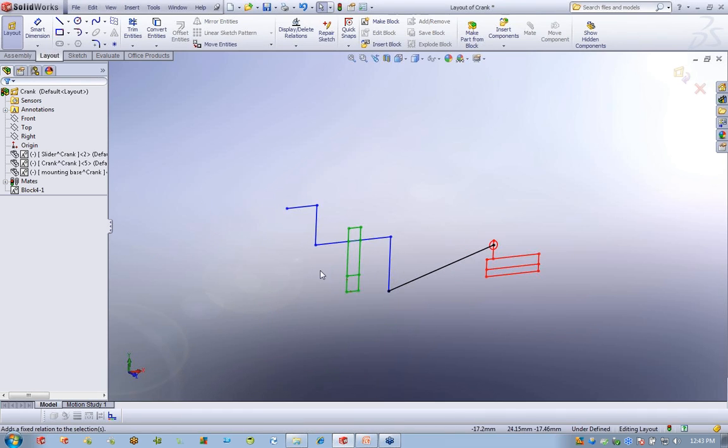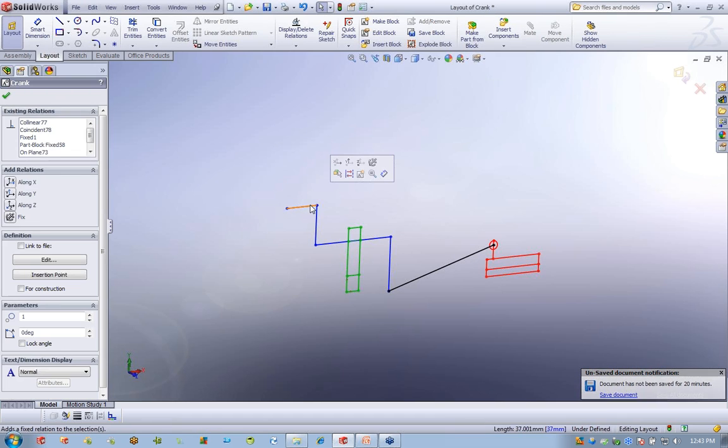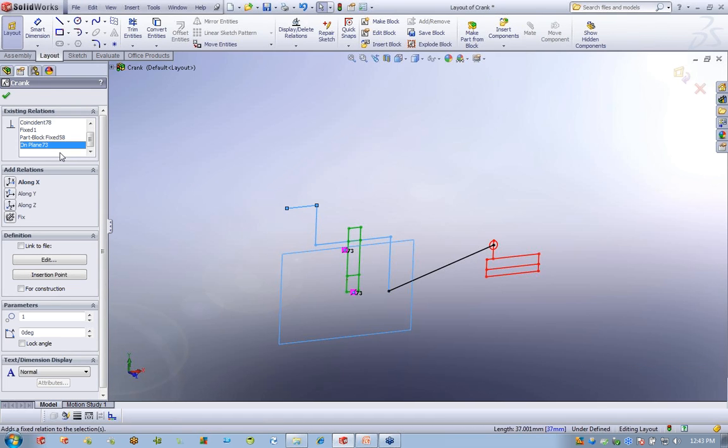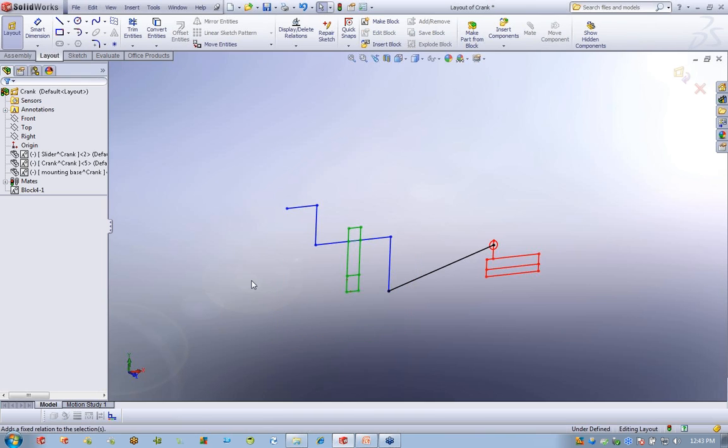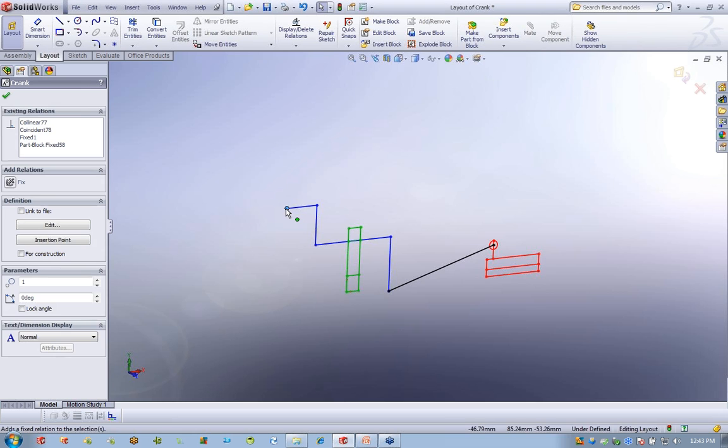Now I can't rotate this handle because this block is tied to a particular plane, because that's what we do when we create these blocks. We tie them to the planes that we're drawn on. But like I said, this is a 3D sketch. So if I decide to remove or delete that on plane, now I'm able to grab the end of this 2D geometry, and hopefully this comes through. I'm able to rotate it in 3D space and actually make this thing work.